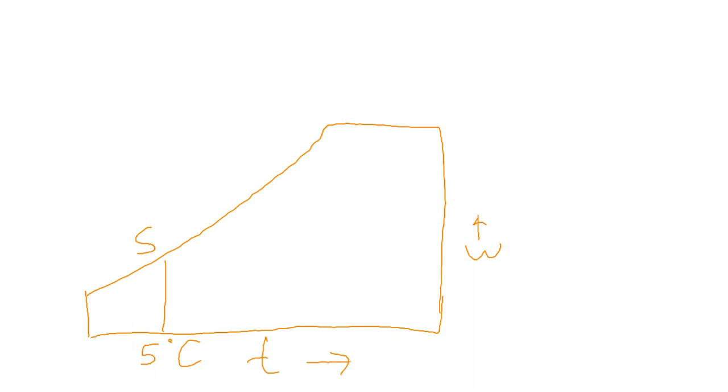And your initial state is known. So this is your condition line. Please consider that this case is on the saturation curve. So this process is your condition line, 1 to S. Now we are interested in knowing where state 2 is. That is the problem: state 2 is to be determined.